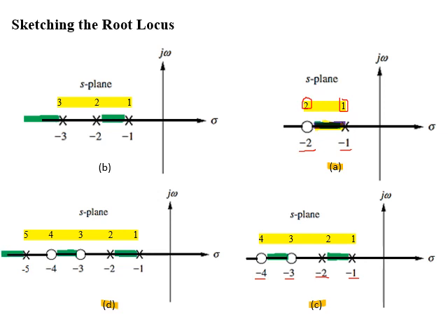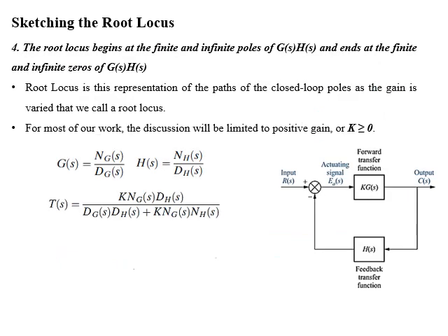And the last branch of root locus will exist to the left of pole at -5. These all branches specify the region towards which the closed loop system poles will move if the gain of the closed loop system is varied. Dear students, Rule 3 defines the region for root locus on the real axis.